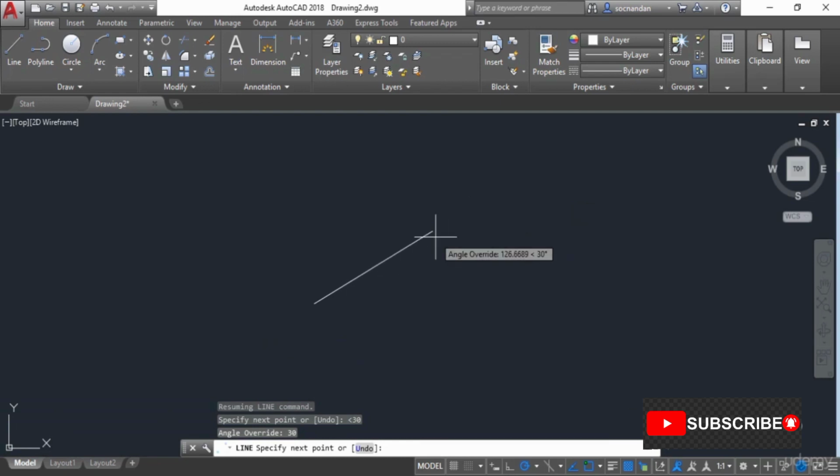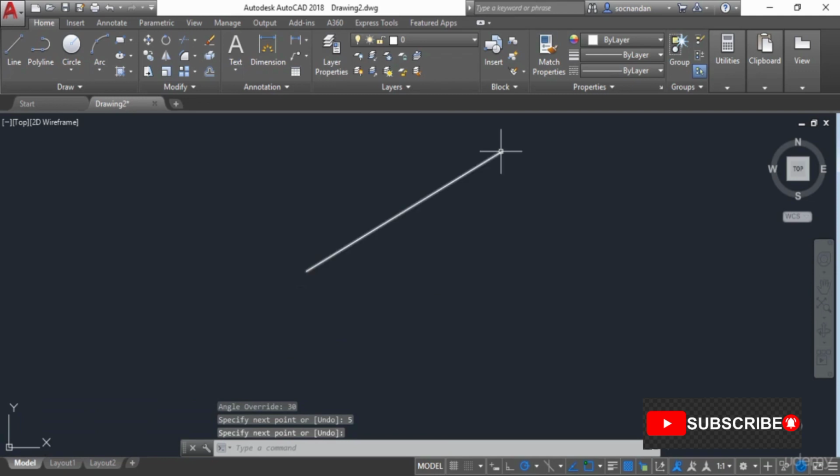Now you need to simply enter the length, which is 5 in this case, and press enter, and press enter again to exit this command. And here we have it, the line of length 5 units, which is inclined to an angle of 30 degrees with respect to the positive side of the x-axis.